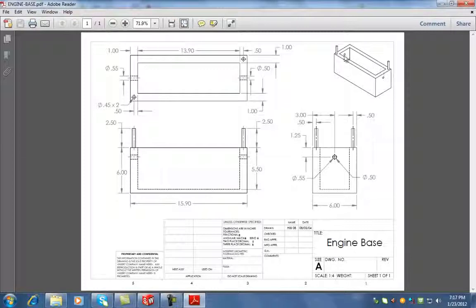Okay? So for example, if your engine is oriented completely different, like those pins are pointing down or those pins are pointing here to the front, that means you chose your planes wrong. We talked about that this plane is the top plane, this plane is the front plane, and this plane is the right plane. That means if we decide to start a rectangle from the front plane, we have to use those dimensions and we have to select the front plane in SolidWorks. Okay? So I hope that everyone is clear on that.